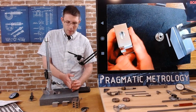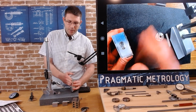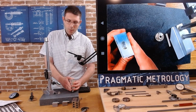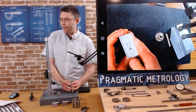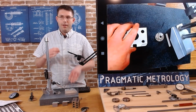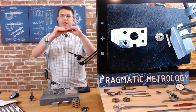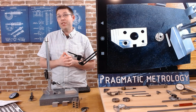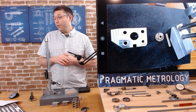There we go. So it's not on the print, but if we wanted to control this slot relative to datum A, and we really didn't care about datums B or C, well, we could call a true position, which by nominal is 0.5 on the angle block drawing. We could call a true position relative to A, and then your circular tolerance zone in two dimensions just gets flattened into a line, and now you have a linear tolerance zone, pretty much just like your plus and minus. There's no difference.